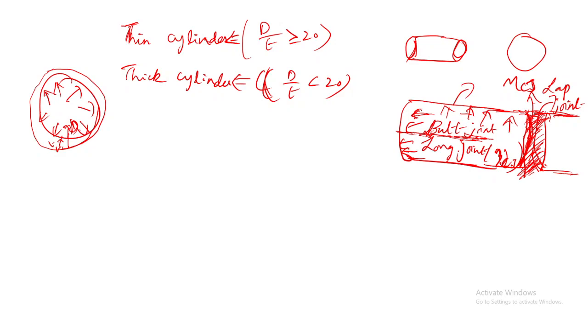Why? Because of the pressure acting inside due to the pressurized fluid, which is greater than atmospheric pressure. Due to this, you will be getting both circumferential stress as well as longitudinal stress. Towards this also you will be getting a stress, and towards the circumferential also you will have one stress. So we have to find out those stresses.